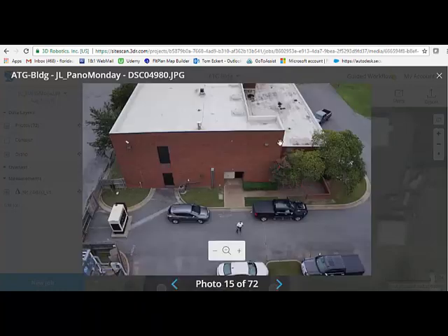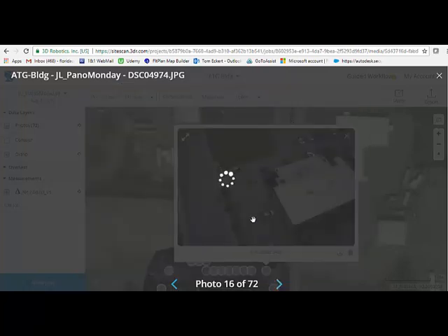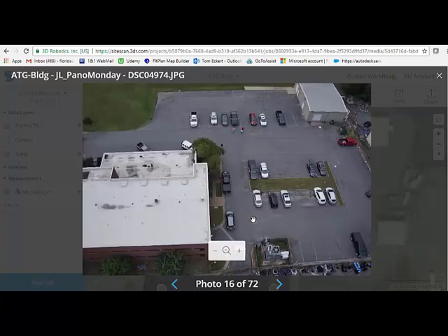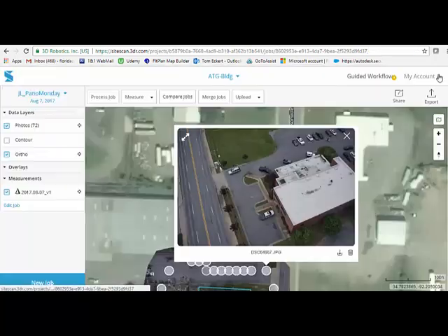But what's nice about this is after you take in the point cloud data, you can replace this facade with a digital still image and then have that material applied in a georeferenced and scaled rotated facade, because ultimately this job is going into Revit. And so this is one of the workflow processes on a collaboration for Revit that we're looking at: the photos and trying to establish some best practices. We'll call them standard procedures on actually using the data.